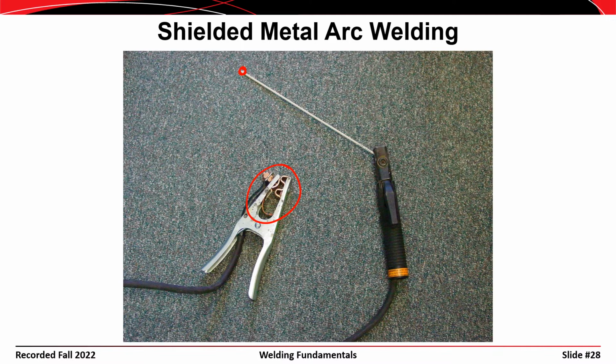One of the shortcomings of this, however, is that when the welder is placing the weld, the electrode changes length during the welding process, which makes it a little bit more challenging, and you have to stop welding every so often and reach for a new welding rod. And if you're placing a long weld, that could be tedious.